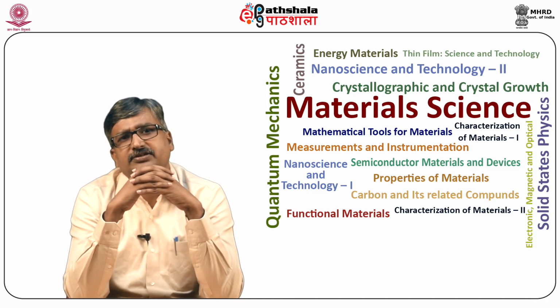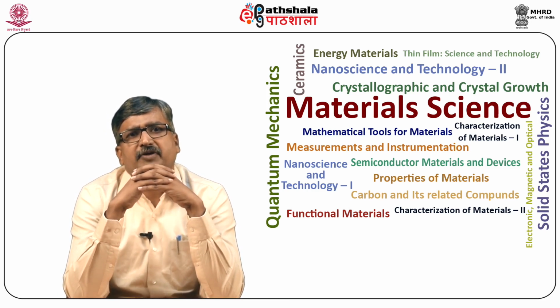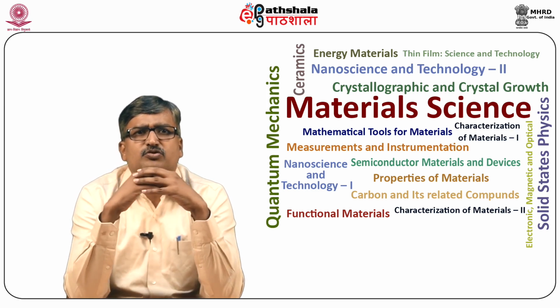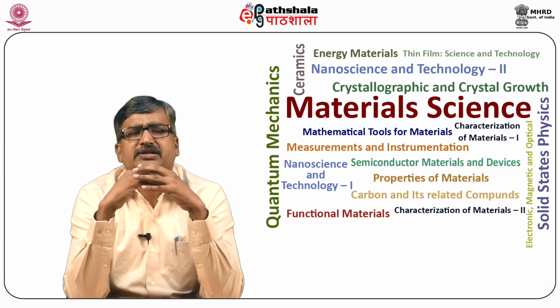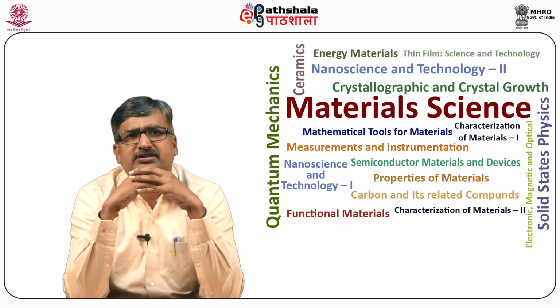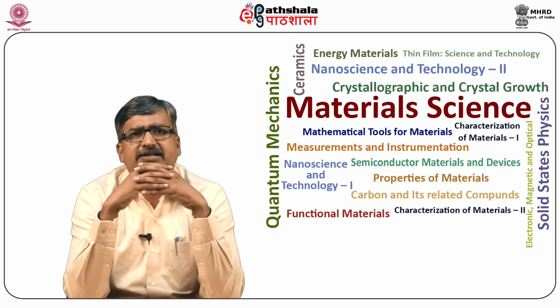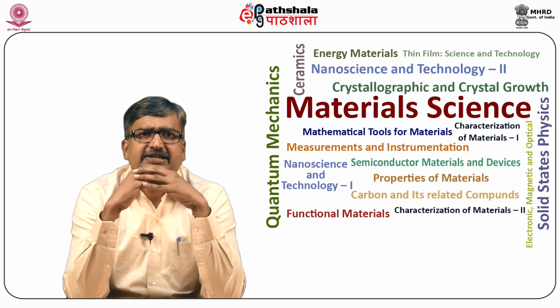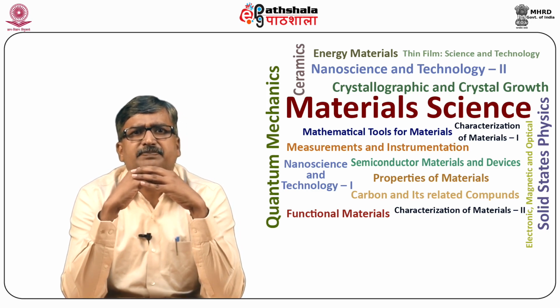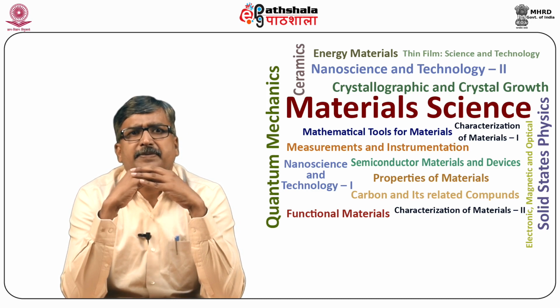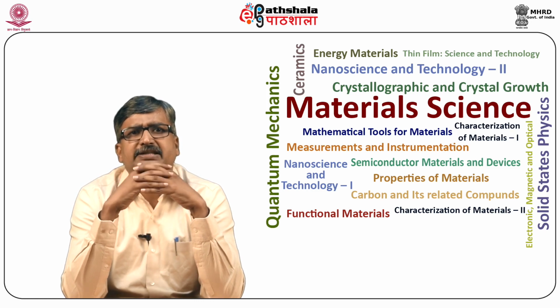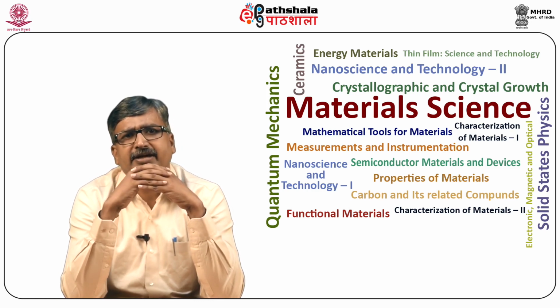As shown in figure A, when the wire diameter of an indium phosphide nanowire is decreased so that it becomes smaller than the bulk exciton diameter, which is 19 nanometers, the quantum confinement effect sets in and the band gap is increased. This results in an increase in the PL peak energy because of the stronger electron-hole Coulombic binding energy within the quantum confined nanowires.